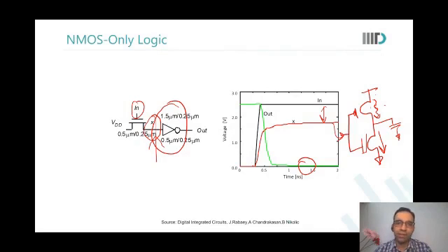On that slide, we had written no static current. But what did we just see? There is all of a sudden static current happening there. Are you able to see this? So we started PTL with a no static current hypothesis, but we just realized there is going to be static current in PTL also.